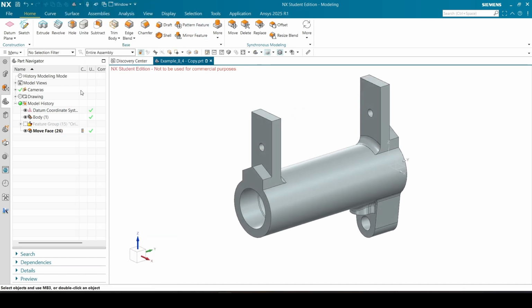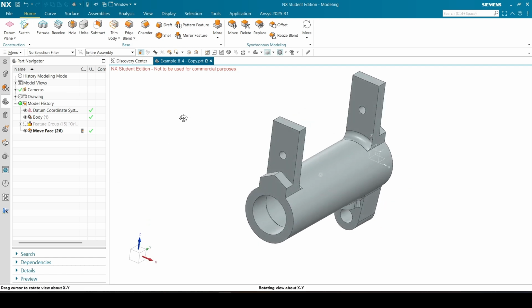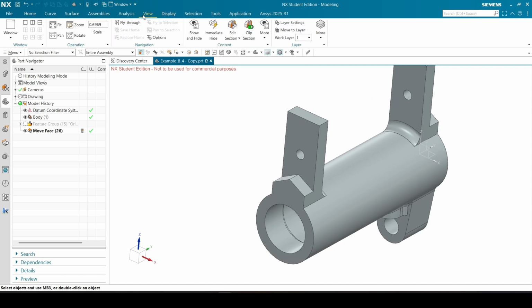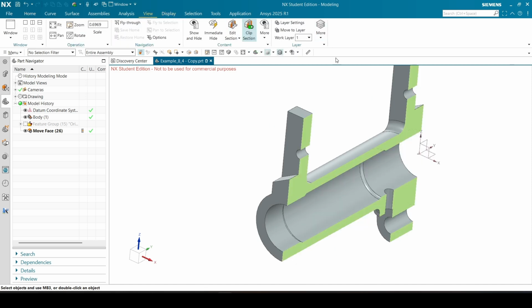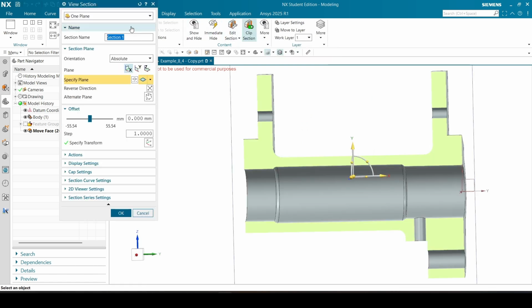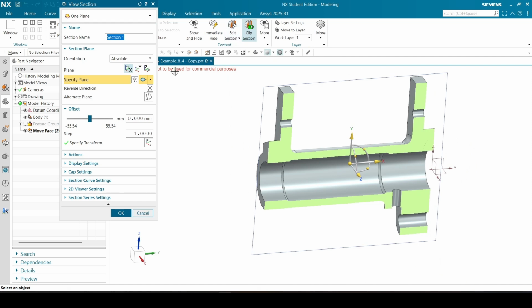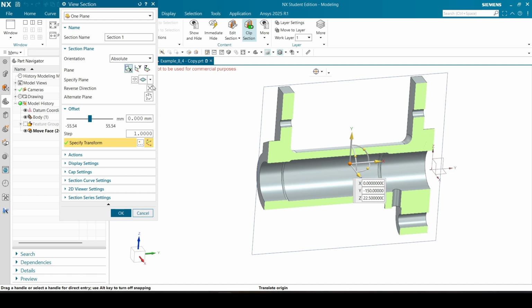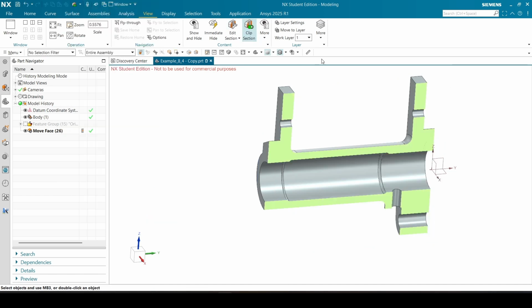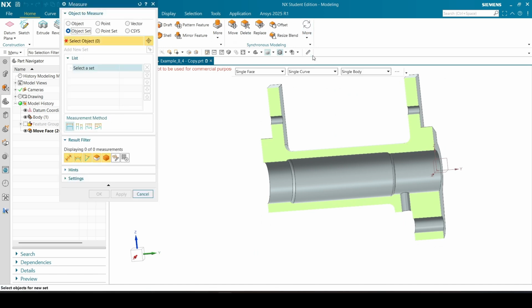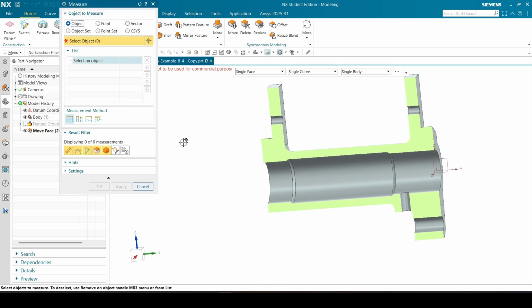Then we also give you a dimension for this inner radius, and you see that's not a reference dimension. First I'm going to change my view to clip section. I'm going to show you how to add it if you don't know. You can add it by choosing edit section and then choosing which plane everything is cut about. That one's good, I'm just going to turn it on again here. It says that the distance, again from the back to that edge over here, is now